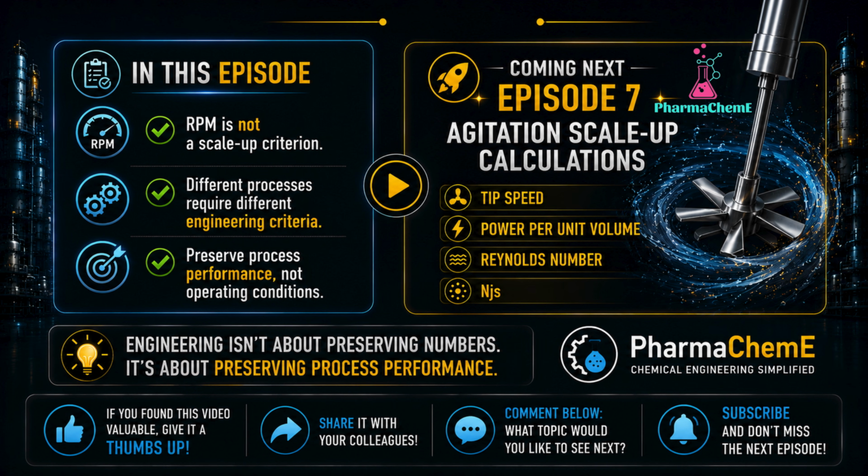Let's quickly recap what we've learned today. RPM tells us how fast the shaft rotates, but it doesn't guarantee the same mixing performance. Different processes have different objectives. That's why experienced engineers don't preserve RPM. They preserve process performance. And that's the mindset that leads to successful scale-up.